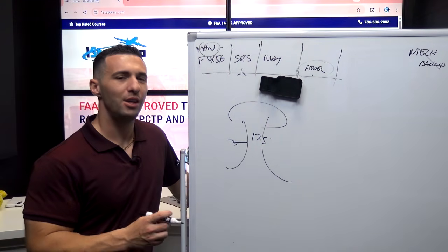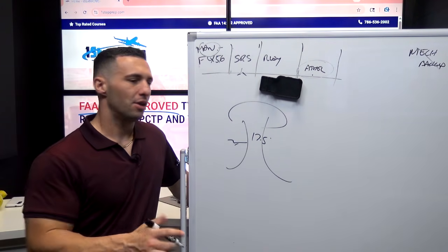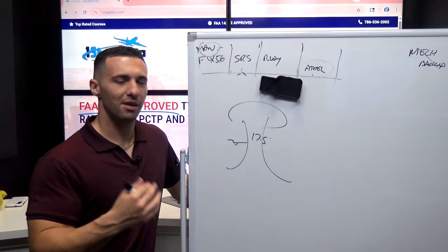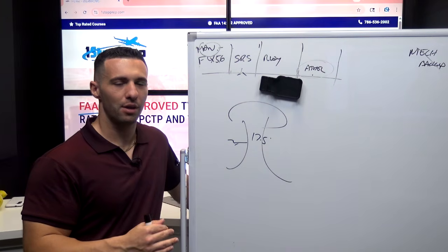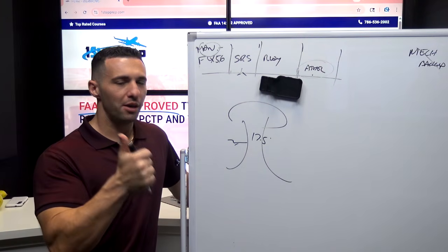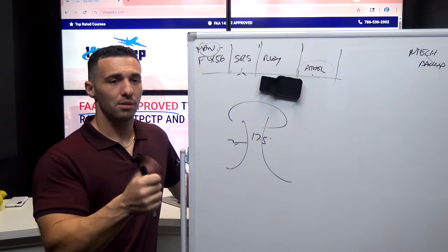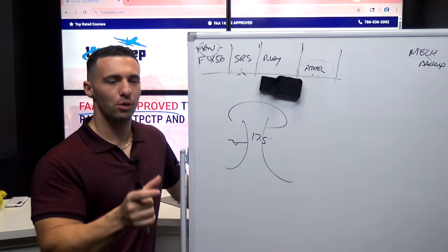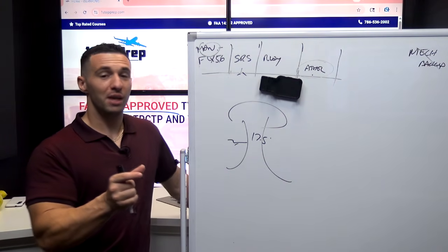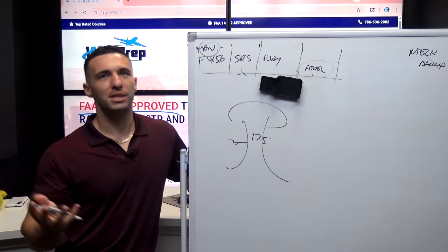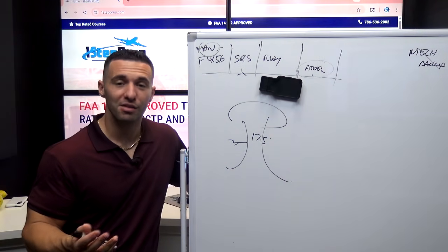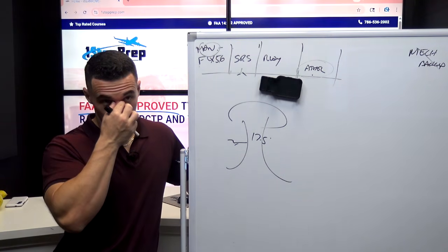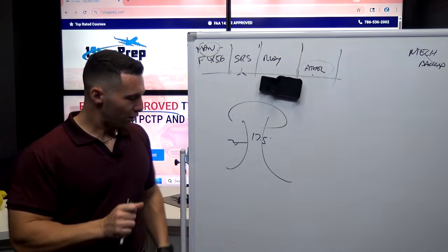You're going to start calling off the radio altitude. You're going to say 500 feet climbing, 600 feet climbing, 700 climbing, 800 feet level, 800 descending, 700 descending, 700 level, 700 climbing. We're not calling it from the airspeed, from the altimeter, right? Because think about the definition of a wind shear, sudden change of wind direction and or speed over a short distance in the atmosphere, which means the pitot-static system is potentially erroneous, considering that what's swirling around the airplane outside is not stable air.